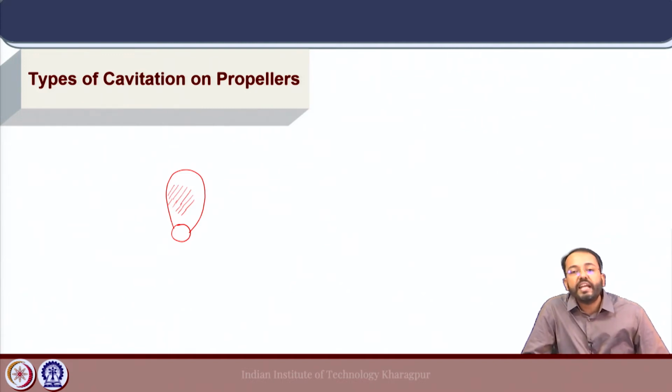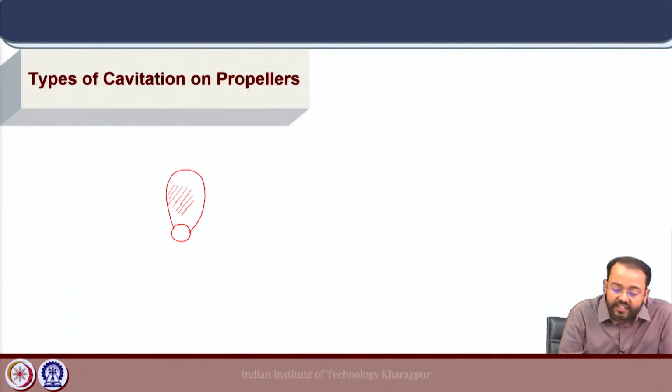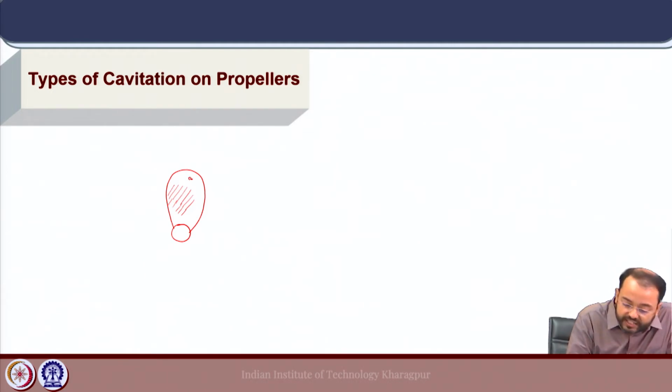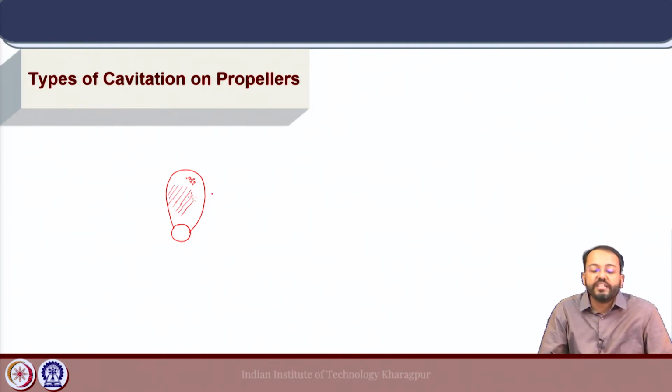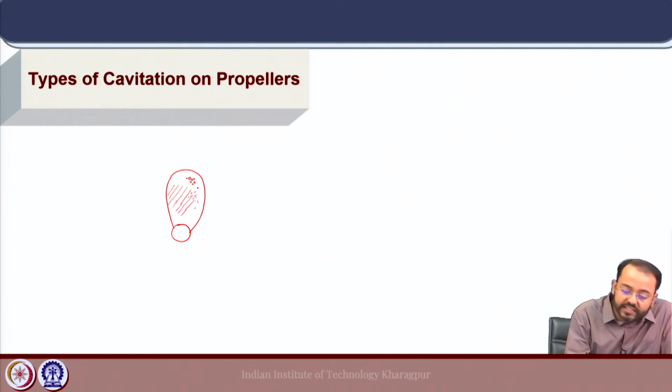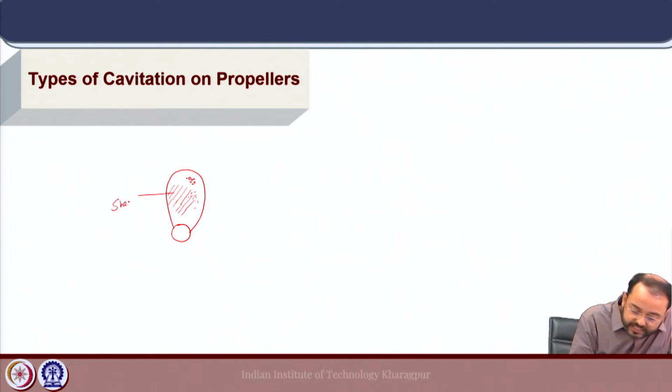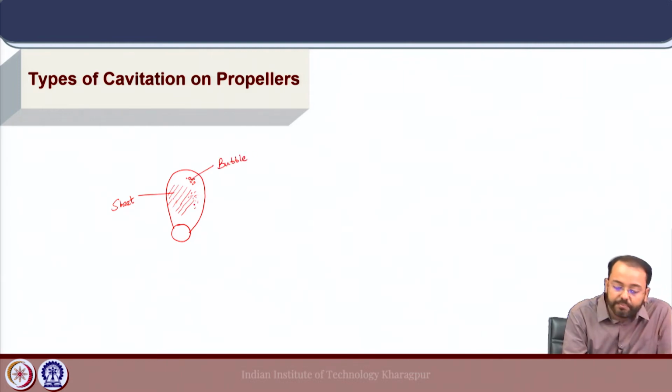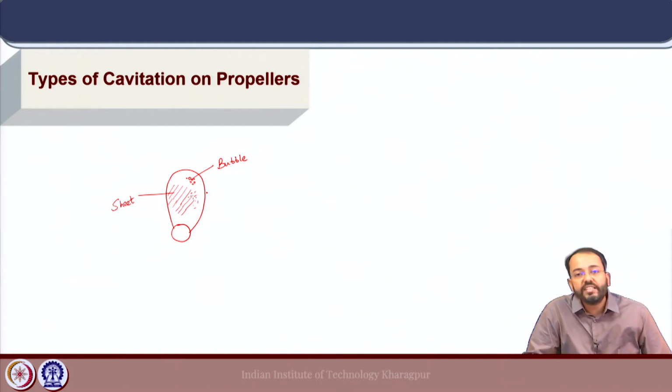Now, the same can happen on the face of the propeller blade if the angle of attack is negative. Other forms of cavitation are bubble cavitations, and at the end of sheet cavitations, cloud type cavitation can happen. So, all these different, for example, this is sheet, we have bubble type, and other local spot cavitation, cloud cavitation, these can happen depending on the appearance of the cavitation bubbles.